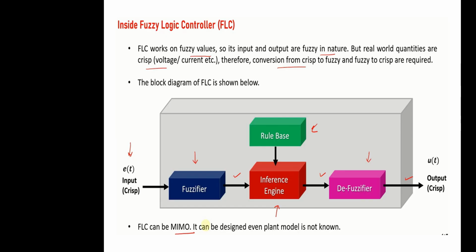Here, we have inside the fuzzy logic controller the following components: fuzzifier, inference engine, the defuzzifier, and a block that houses the rules that the inference engine makes use of, so as to be able to give a logic output.